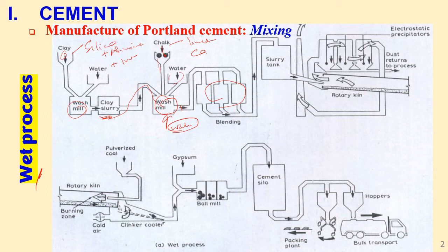In this blending section, they are mixed mechanically in the storage tanks, and the sedimentation of the suspended solids is prevented by bubbling air. You don't want the suspended solids to settle at the bottom, so there is bubbling of air. As a key, the solid arrows show the flow of the raw materials in the process of manufacture, while these other arrows show the flow of air. Once they are blended, ensuring no sedimentation occurs, the mixture is taken to the slurry tank.